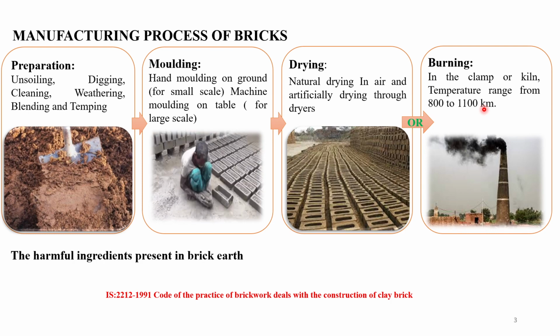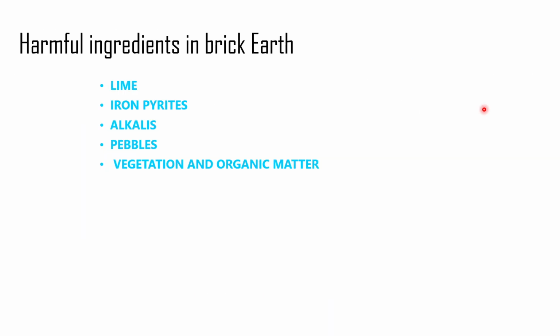So for avoiding this, there should not be any vegetation or organic matter in the brick earth. We have already discussed the excess quantity of lime, and lime is harmful in brick.